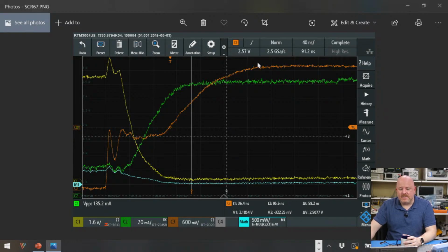Believe it or not, this is actually typical of a MOSFET turn on. And this actually illustrates why MOSFETs are not as simple as looking at the threshold voltage, and that's how you turn it on. One of the things we want to control is how fast it turns on, and we do that by controlling how much current goes into it, because this is showing us a capacitor charging up and then another capacitor charging up. Okay, anyway, I'm getting ahead of myself.